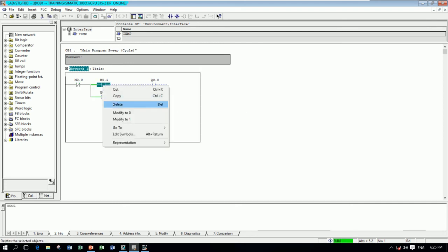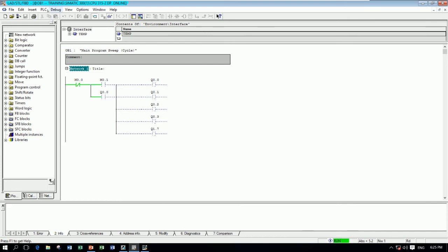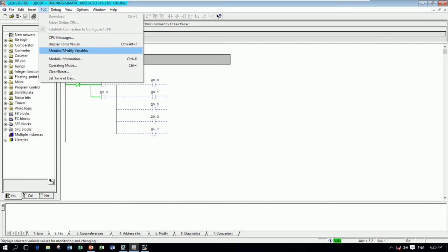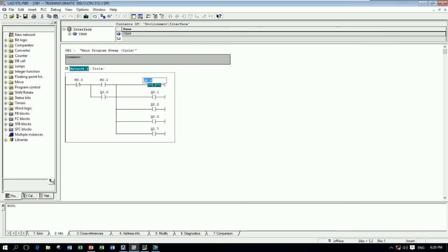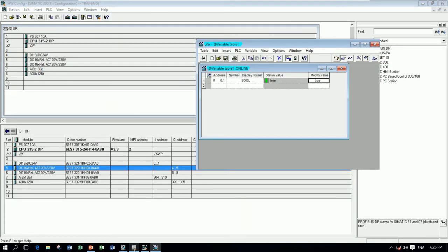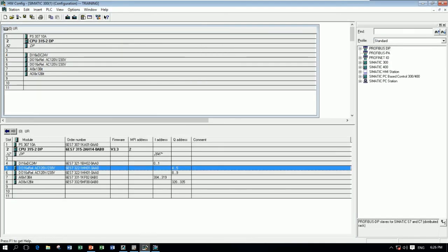So when I turn on M0, normally we can do it like this. Go to the PLC data monitor, yes, we can write M0.1, yes, and then go online, and then write this one to 1, and then click this one, yes. You see the button is on, yes, and this one should start from 4, right? Because this one is 4.0, yes.